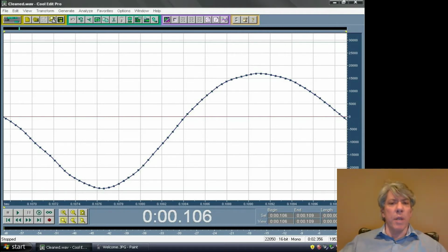Let's take some simple numbers. Let's say you did want to measure from 0 degrees Fahrenheit to 65535 degrees Fahrenheit. I don't know what case you'd ever want to do that or what sensor you would use, but let's just pretend that's the case, and you use a 16-bit analog to digital converter to do it. Well, then each step, each change in the number, each 0 to 1, 1 to 2, etc., would represent 1 degree Fahrenheit.